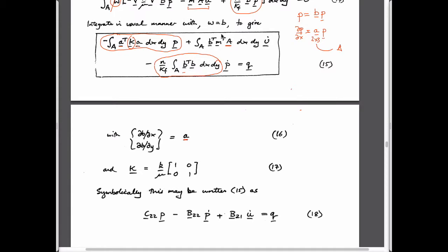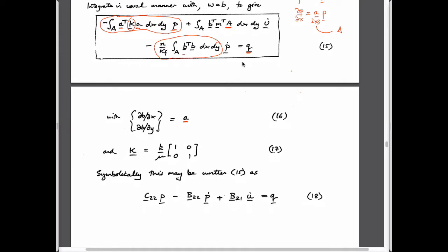So perhaps it's worthwhile stepping back and realizing that we have something which relates to fluid pressure and something which relates to flux. So if we write them out using all of these components, we have a portion that relates to fluid pressure, which we'll call this. A portion is equivalent to nodal fluxes, and we have parts which relate to the mass, the rate of change of strain, and the rate of change of fluid pressure, which are just individual matrices that get added to this.